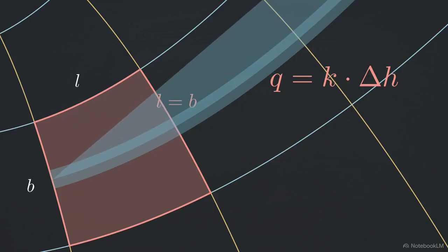To see how this calculates flow, we look at its fundamental building block, the elementary square. This isolated shape has two variables, a specific vertical length and horizontal width. Because of the strict right-angle rule, we draw the net so these dimensions are perfectly equal. Applying Darcy's law, flow equals permeability times hydraulic gradient times cross-sectional area. Gradient is head drop divided by length. Area is width times unit depth. Because length and width are equal, they cancel. Flow through any square is permeability times head drop.